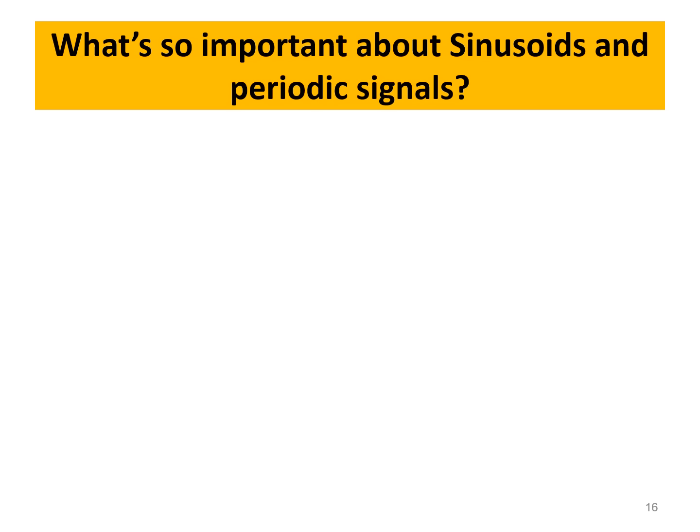Instead of looking at the time domain, I can look at the frequency domain and tell which frequencies are there. Now, if you want to filter signals, and there is noise at a specific frequency, you can design a filter to remove that frequency. So that's why we like to use the frequency domain and break down to the sinusoids, in order to be able to do filtering and remove noise, and also simplify our analysis.